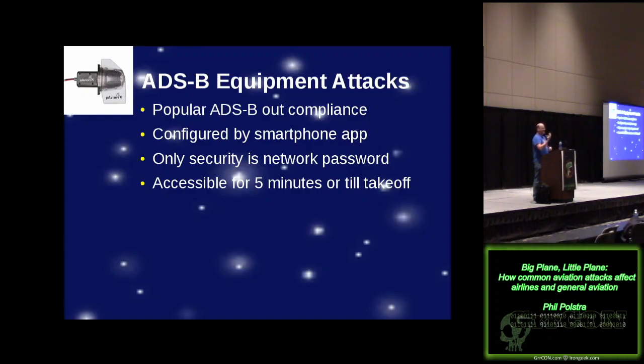Even the gyros in it. Normally they're vacuum driven, with a pump on the engine that creates suction, which spins these things. Nope, we don't need anything like that. We have these Venturi tubes on the side. So it works great, but only after you've been flying for about 10 minutes. So if the weather is kind of low, you better taxi up and down the runway a little bit and get those things spinning before you get up in the clouds and find yourself not sure which way is up.